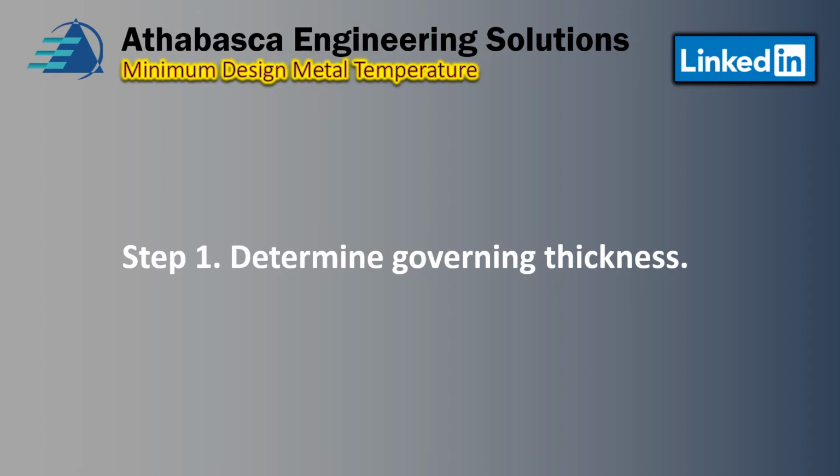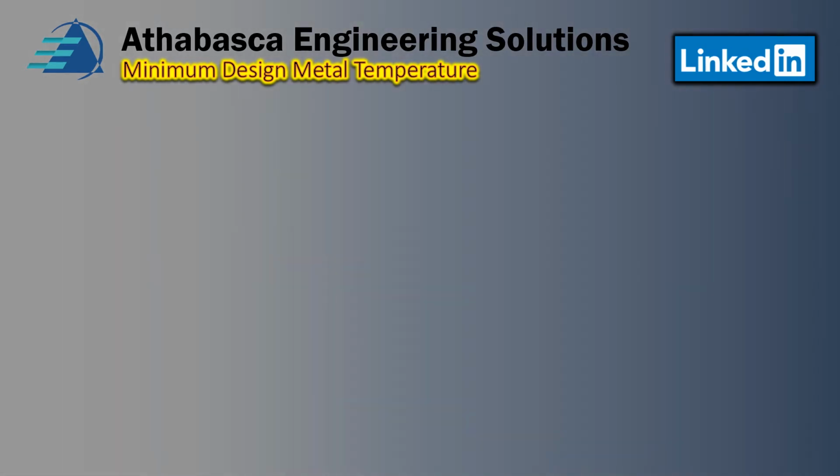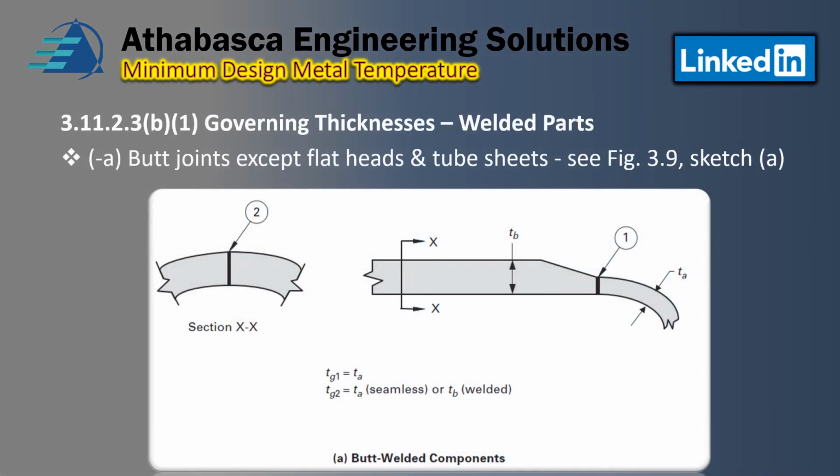And the section to refer to is 311.3b in the 2021 code. See that in 311.3b, there's governing thicknesses for welded parts, and there's another section for non-welded parts. They have a series of sketches, and what's nice is everything is self-contained in Division 2. So they have their own figures, even though in a lot of cases they're identical to Division 1, but you don't have to start mixing and matching your references. You can stay within Division 2 and work within it.